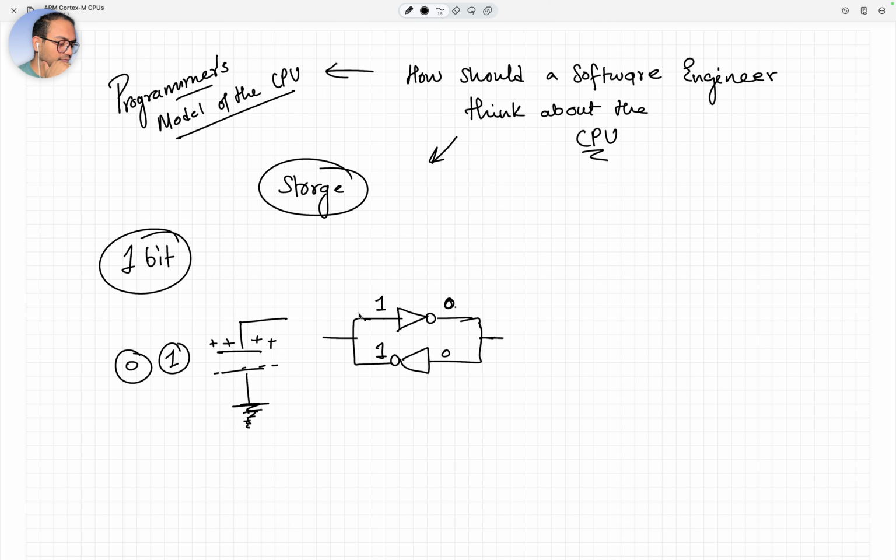So whatever value you provide here is trapped in this circuit. And as long as the power is available, if we had a circuit like so, from where we read the value, this would read as 1 because this is 0, right? So we can say 1 is trapped in a feedback loop, in a circuit.